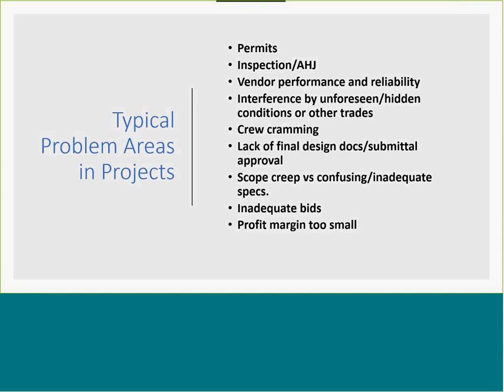The problem areas that project managers really run into are on this list. It's a longer list, but project managers have to be able to tackle these and be prepared for them. These generally should not be seen as surprises when they go south on you, because it happens so often. Permits, inspection, performance and reliability issues, interference by unforeseen conditions. Prices go up on materials, some sub doesn't show up, all kinds of things.